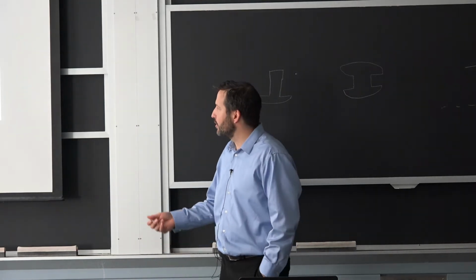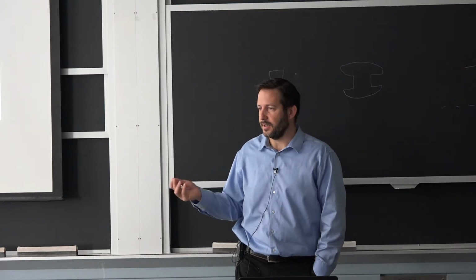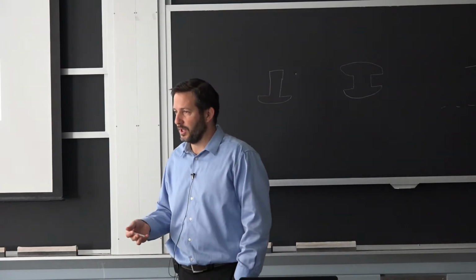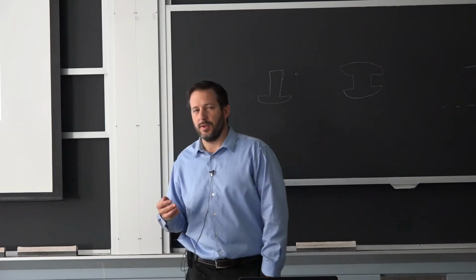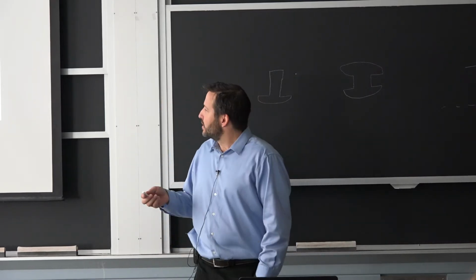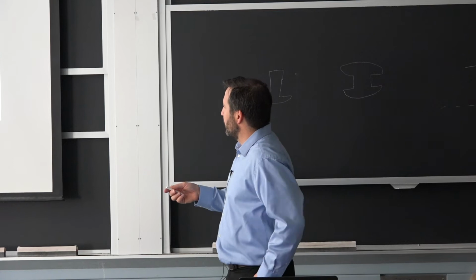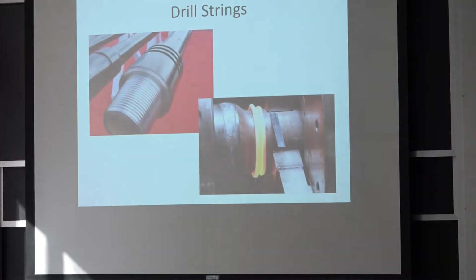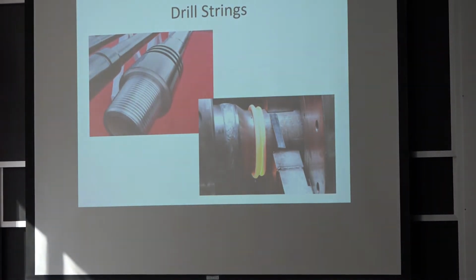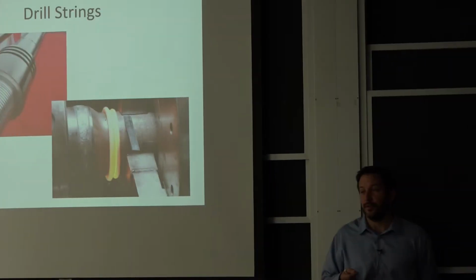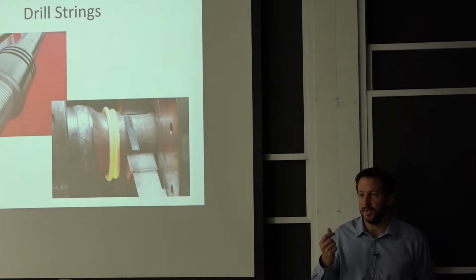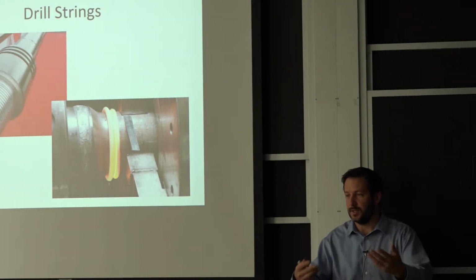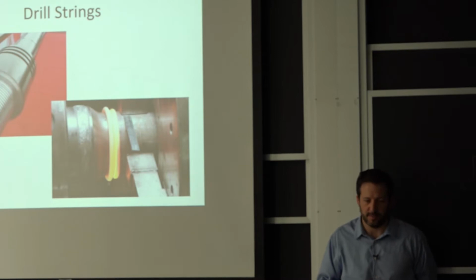So those materials are in the 100 KSI type range. They went through a heat treatment. The welding of them is very important. So in this case, it's a friction welding that they have been using, where you are able to do it quickly and you don't change the microstructure as much. You still have to do a heat treatment after the fact. So the only way to make this equipment is to fully assemble it and then do a final heat treatment to get the best mechanical properties.